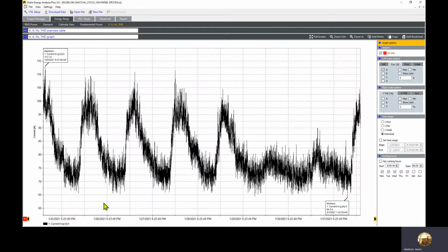If I click this, it's going to put in some little markers noting where the min and maximum for the average is. This is your highest average, the maximum. We can right click on this and go to move, so I can drag this into a more visible position, not tucked off in the corner of the screen. Down here, I'm going to delete the minimum because we really don't need to see that information.